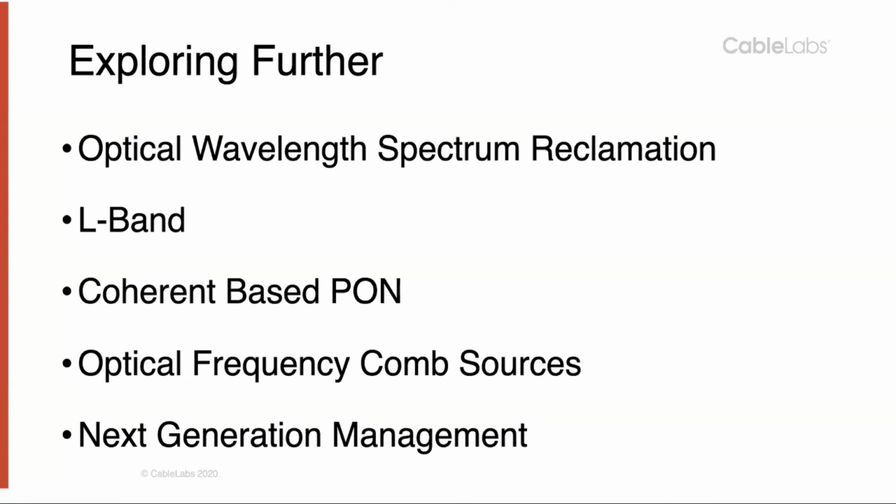In the access, because we are dealing with much shorter distances that are non-amplified scenarios, we can introduce L-band and not wait until amplification in L-band becomes popular. We have that in coherent optics, the costs are coming down, and we see that in the future they're also going to play a big role in PON technology. We can take advantage of the superior performance of coherent-based technologies to have much greater performing PON systems.